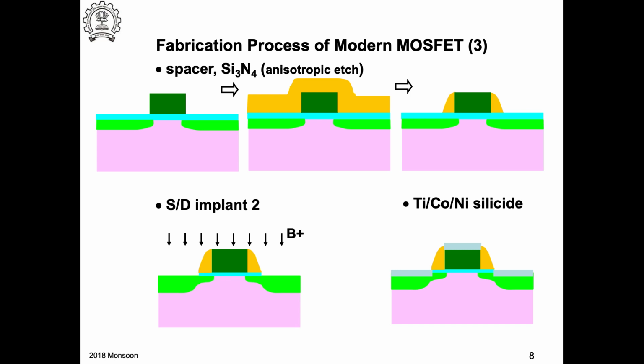So it depends on what you are implanting through. If I'm doing an implant through metal, for example, gold, usually you don't use gold, but it's much heavier compared to silicon. So the ion stopping power of gold will be more than that of silicon. This is just to capture this difference in the stopping power, because we talked about 2 different types of stopping mechanisms. One is the nuclear stopping. The other is electronic. Electronic, we have 2 types. These 2 materials may just have 2 different stopping powers. Otherwise, if they had the same stopping power, it would have just continued the same shape.